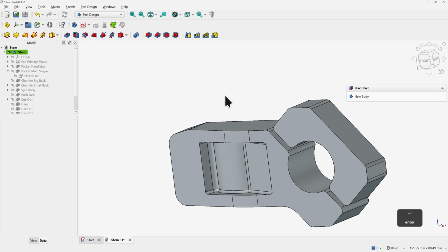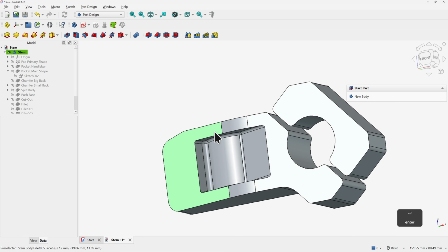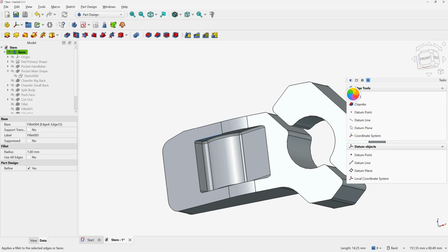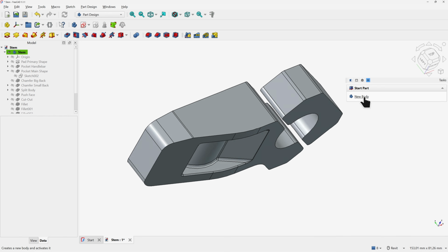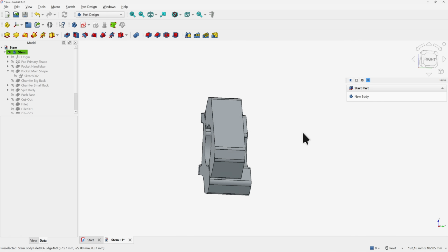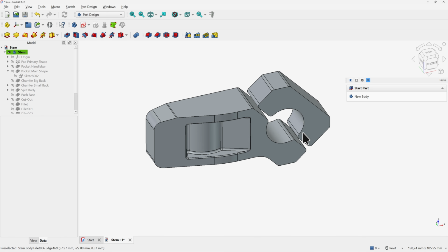Just one last fillet to create, I promise, and you won't hear me mention fillets for the rest of this tutorial. We're going to select one edge of the contour and give it a 0.5 mm fillet to smooth everything out. I don't know if you agree, but this tool really has a magical touch. It can turn a plain, straight, boring shape into something truly interesting and professional, and that's just in a few clicks.